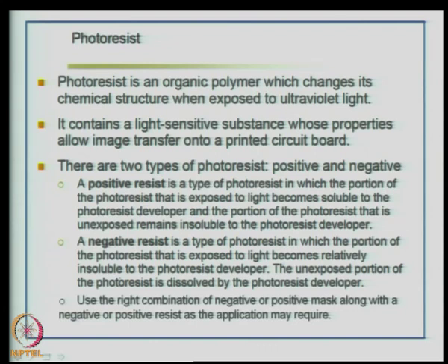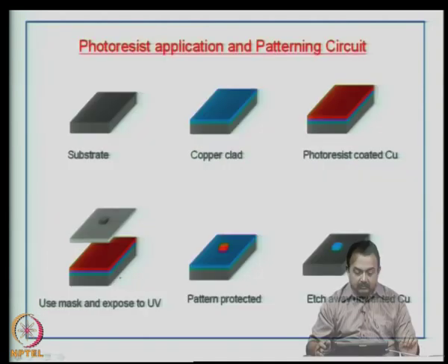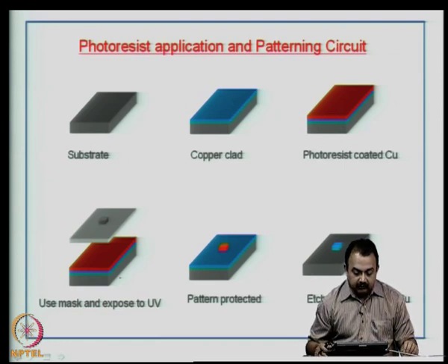So, you have now two materials, negative and positive resist, and you have two photo tools, positive and negative photo mask. So, how do you use these and when, for what kind of application? Before that, a photoresist application and patterning circuit in terms of illustration is given here.